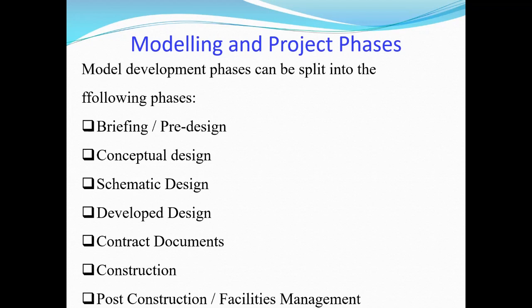So the engineer decides, okay, I go with the one-way beam slab system for the superstructure and substructure. If the soil condition is not good, I may need a deep foundation, pile foundation. They then need to design bored piles or whatever, depending on the site condition and so on.